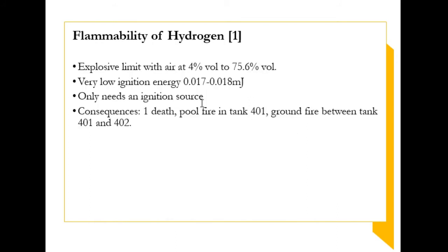With the flammability of hydrogen in air being 4% volume to 75.6% volume and requiring only a very low energy, 0.017 to 0.018 millijoule, the buildup of hydrogen only needs an ignition source. It caused one death, a pool fire in tank 401, and a ground fire between tank 401 and 402. Next, I will pass to Silke for his presentation.